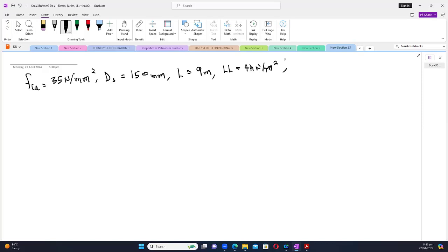So the partition loads are usually the walls which are not structural, or it could be, let's say, glass, or these days a ceramic or a wooden material, dividing maybe the rooms into smaller divisions. At the end of the day, when these things are there, they will stay there permanently throughout the whole purpose of the building. Unless maybe there's regular maintenance, or for some reason they want to make the rooms bigger, then they will dismantle the wall or the wooden divide and make it bigger. But at the end of the day, it will be there for months and weeks or years.